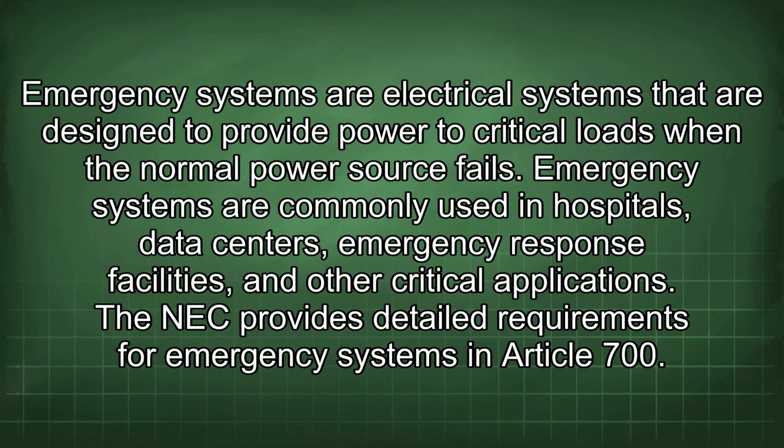Emergency systems are electrical systems that are designed to provide power to critical loads when the normal power source fails. Emergency systems are commonly used in hospitals, data centers, emergency response facilities, and other critical applications. The NEC provides detailed requirements for emergency systems in Article 700.